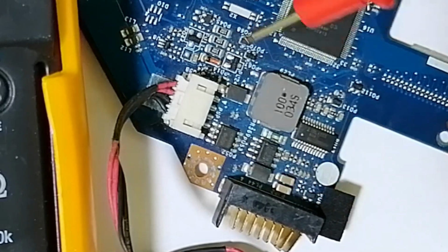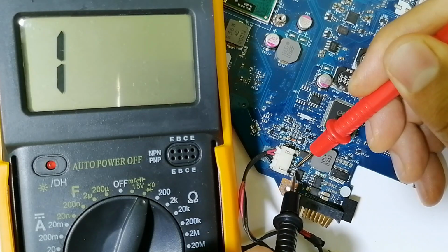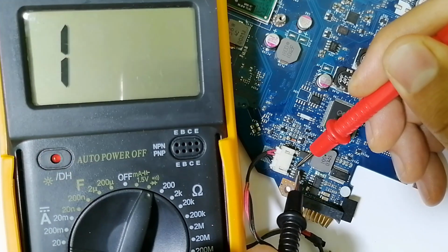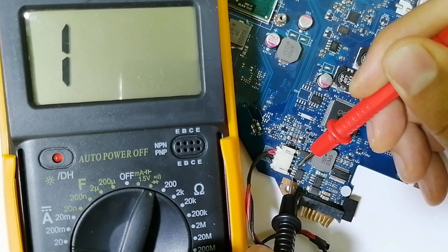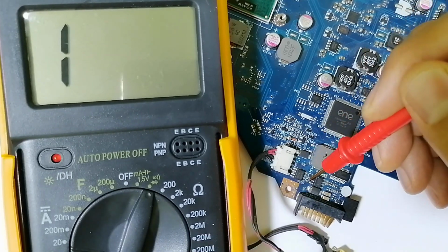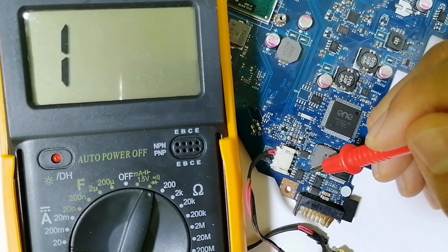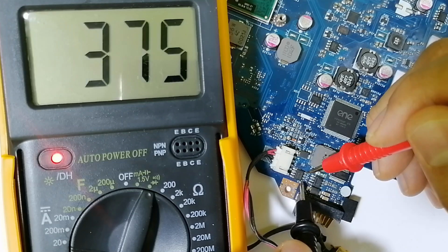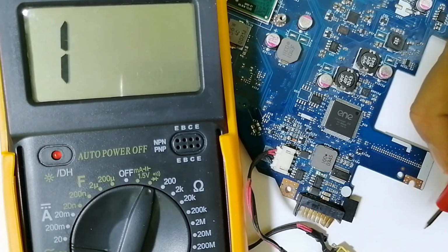If you want, we can even check. Let's put the probe here and check with the second pin and the 3rd pin, as you can see. So these 3 pins are connected together, but this is the gate. It's not connected with the other 3 pins. And over here, these 4 pins are connected together. Why? Because this is the drain. So let's check. This is the second pin, the 3rd pin, and the 4th pin, as you can see. So 4 pins are connected together.